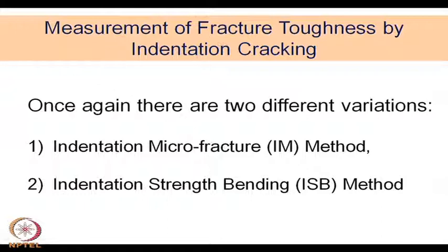There is another technique, measurement of fracture toughness by indentation cracking. Instead of creating a notch, one can generate some cracks by indentation. We have seen earlier that hardness can be measured by indentation, and we have also mentioned that during hardness measurement there should not be any crack. The indents should be created under optimized loads, so that no crack is generated.